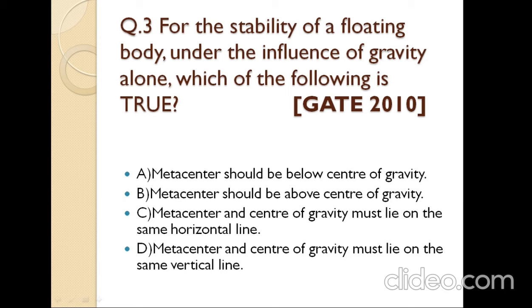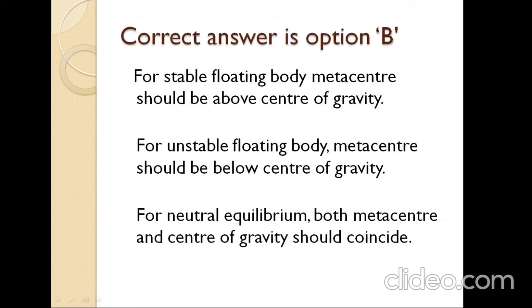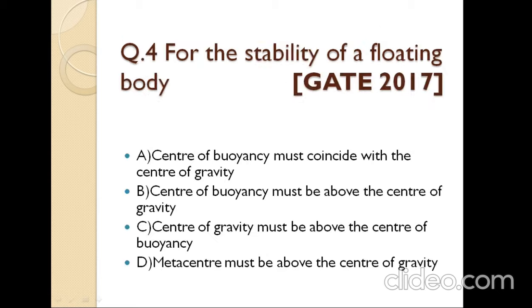So correct answer is option B. For a stable floating body, metacentre should be above center of gravity. For an unstable floating body, metacentre should be below center of gravity, and for a neutral equilibrium, both metacentre and center of gravity must coincide.